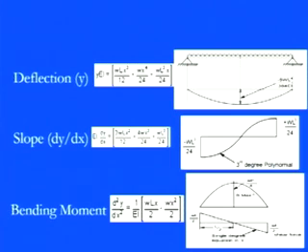With these slope conditions, if we put in those values, as I told you in the previous section, the slope is always 0 where the maximum deflection is, and we get the maximum deflection at x equals L by 2. You can see the convention here goes from positive to negative. At this particular point, where the maximum deflection is, the slope is 0.